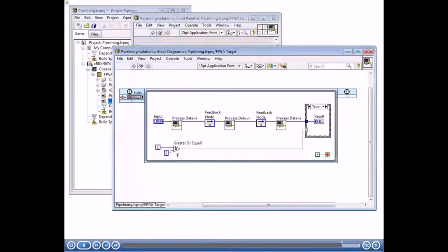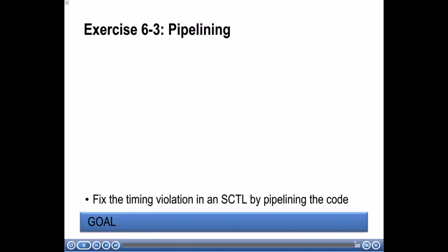Okay, so over here, just like we saw in the previous slide, this is just some code to only output a result after we wait until the third iteration and later to actually output a valid result. Now you can use pipelining to increase the throughput or speed of a single cycle time loop. Next, we will define fixed point data type terminology.